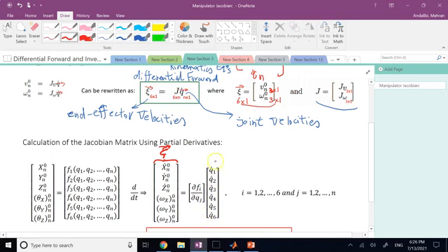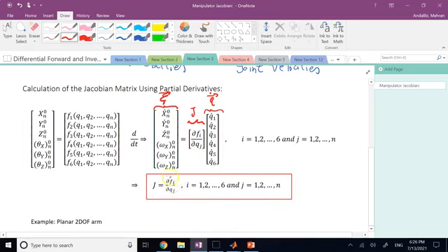So this is clearly your vector q dot that you have up there. So you see that your zeta is some matrix times q dot, so that matrix has to be your J matrix. So clearly the Jacobian is the partial derivative of each one of these functions with respect to one of the variables. Okay?